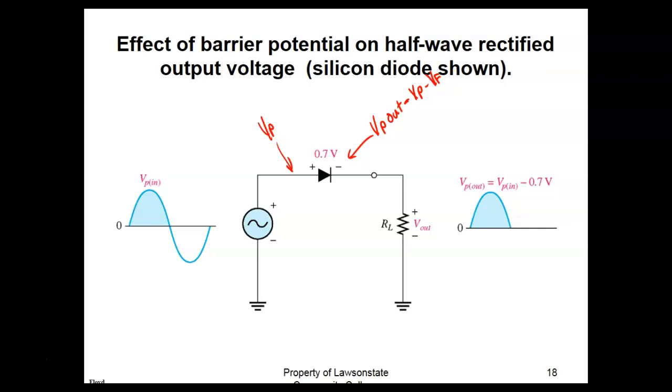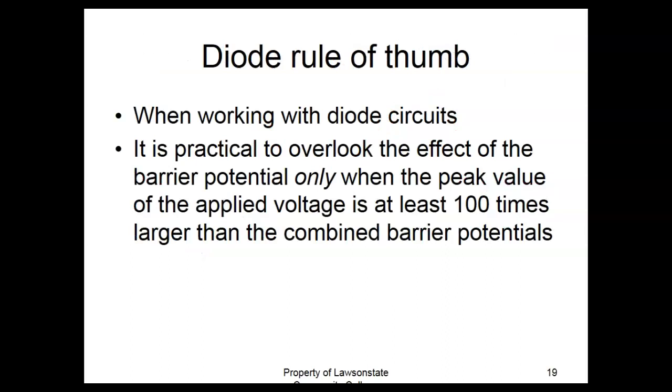And on high voltage power we can ignore this, but when we play around with the low voltage like we're doing in our class, we're going to take out approximately 7/10. We're using what we call second approximation. So we're going to take out 7/10 for silicon and 3/10 for germanium. And y'all can see just by our calculations, this has been really accurate.